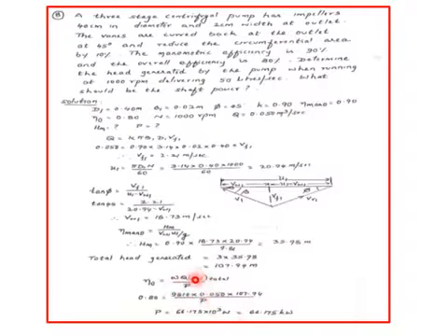The overall efficiency is for the entire multi-stage pump, so 0.8 equals rho g Q H total over shaft power. Q is 0.05 because the same discharge passes through each impeller, whether you take multi-stage or one impeller. So Q is 0.05 and total head is 107.94.